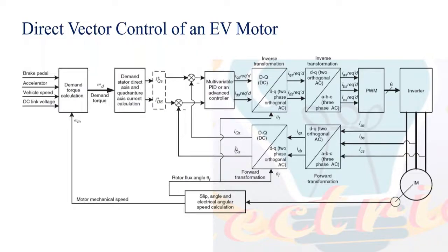And a very important thing which I missed: to get the mathematical transformation, the Park transformation, a very important value is the rotor flux angle. That is why we call it sensor-based FOC or sensorless FOC. Sensor-based FOC is what is most widely used in electric vehicle applications. We have a sensor that determines the position of your rotor flux, and based on the sensor information, you will have a lookup table inside this forward Park transformation. That lookup table will tell you what is the sin theta and what is the cos theta position.